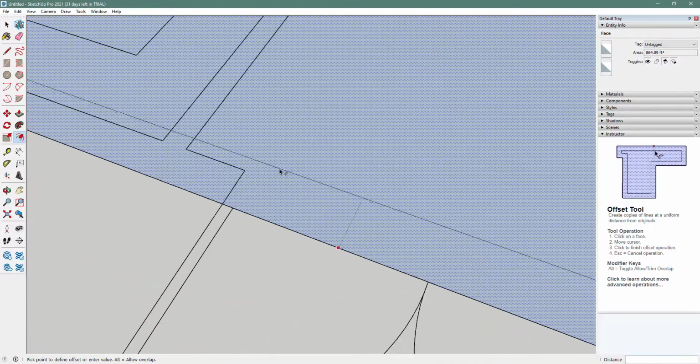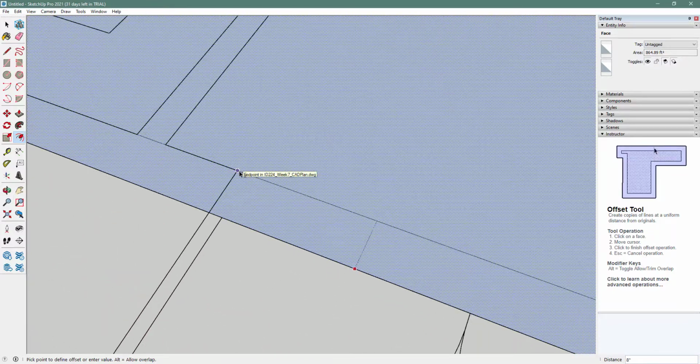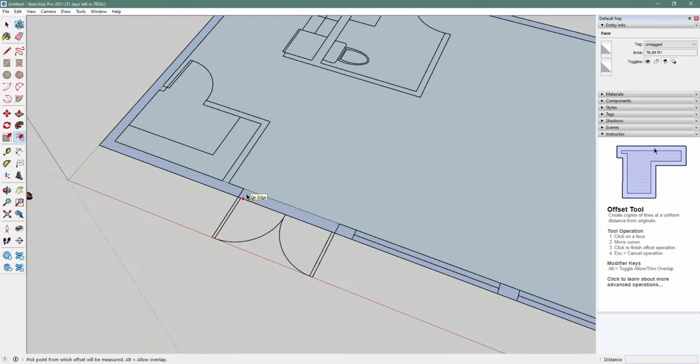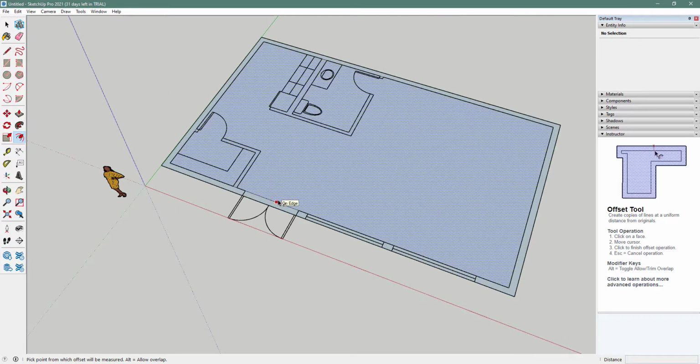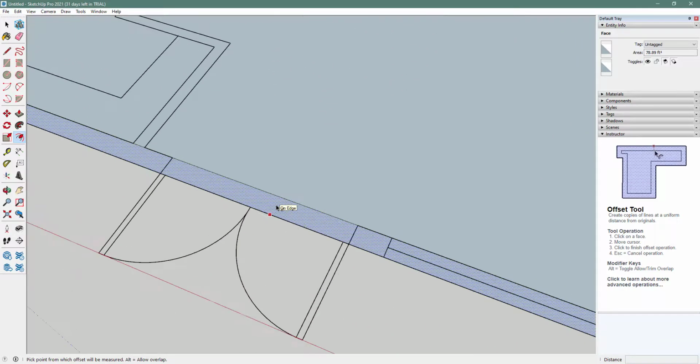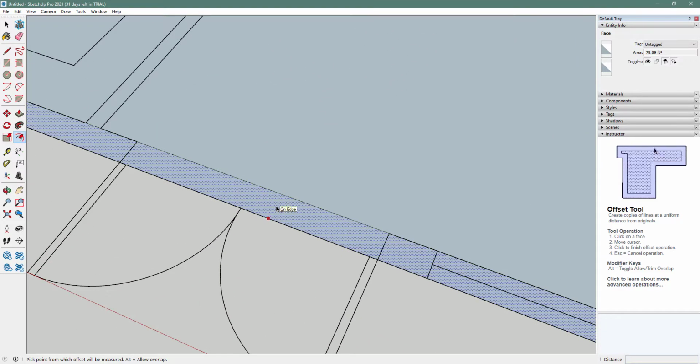I'm going to hover over this interior corner of the doorway, making sure I get that purple circle, and then I'm going to click. What that does is it separates the floor from the walls. If I pull back, you'll see that all of your exterior walls highlight when you move your mouse over it. You can tell it's highlighting because it's got those little tiny dots. Once you can see that there's a separation, now it's time to raise those walls up off the floor.